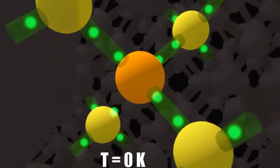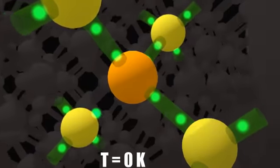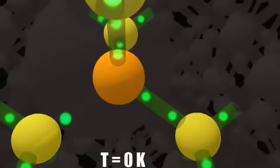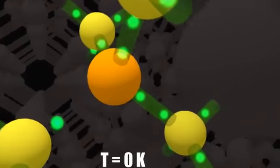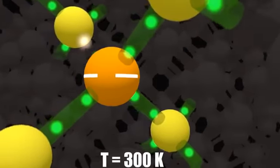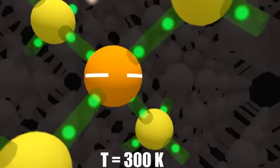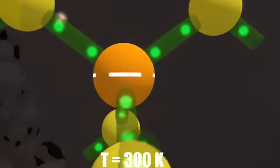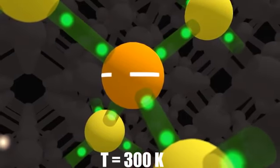An impurity with only 3 electrons in its outer shell can also be used. The 3 outer electrons complete 3 of the 4 bonds. The 4th bond remains unoccupied. However, at room temperature, the electrons from other bonds can move in to occupy this free space, creating a hole in the material and a negatively charged impurity.